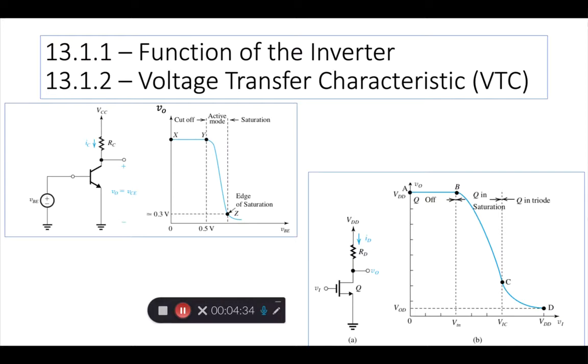Now there is a transition phase where you go from being high to low. In that phase, sometimes we'll enter saturation or active. But generally, when everything is stable and the input is high or the input is low, then the devices themselves are either off or in triode for CMOS. We don't do a whole lot of BJT switching stuff, BJT logic circuits. It's possible to do it, and they used to be done previously, but now almost everything digital has moved to CMOS. So I'm just going to focus on the MOS style digital circuits, logic circuits.